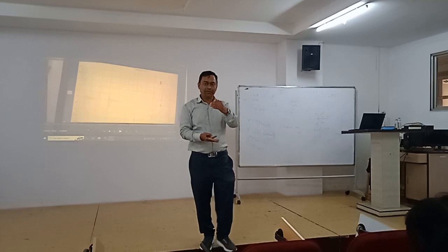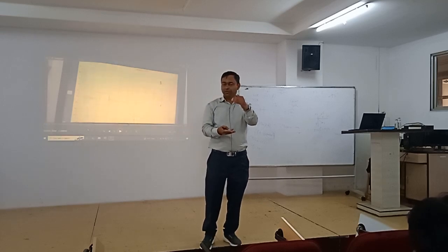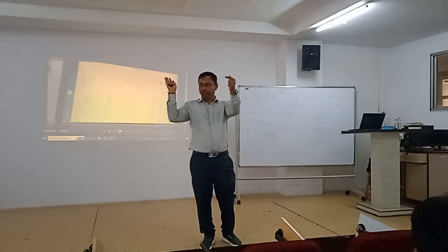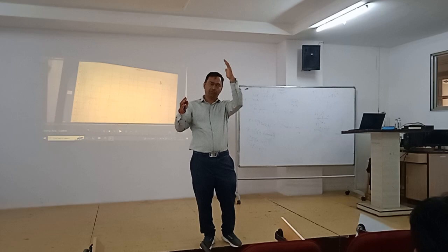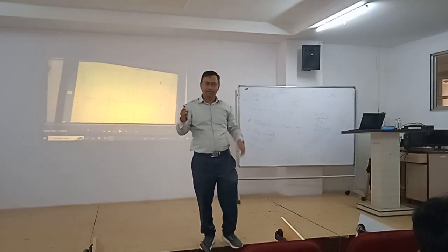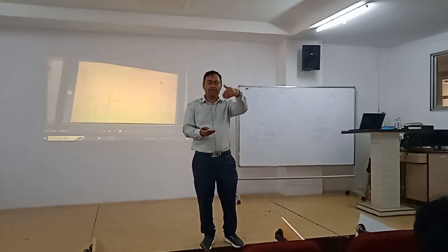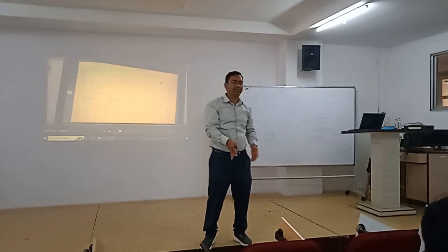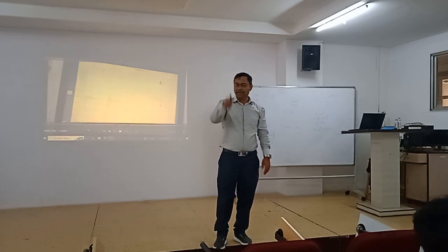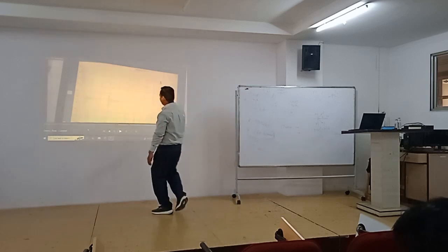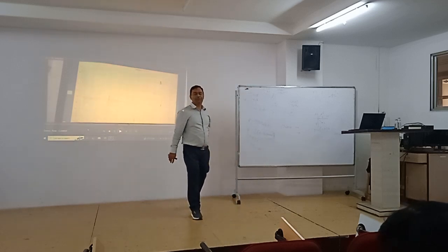Because now flow is 0 and desired flow is 50. As soon as you open it, the motor is moving at high speed, so the flow will be very high. It may reach more than 60, 70, 80, 90. Desired flow is 50 and actual flow is 90, so it will decrease again. It will keep on happening till we achieve the desired value of flow.